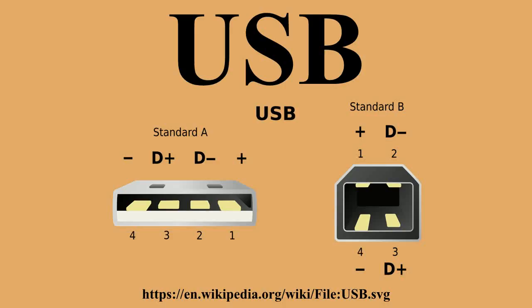An alternative to this is a compound device, in which the host assigns each logical device a distinctive address and all logical devices connect to a built-in hub that connects to the physical USB cable. USB device communication is based on pipes. A pipe is a connection from the host controller to a logical entity found on a device and named an endpoint. Because pipes correspond one-to-one to endpoints, the terms are sometimes used interchangeably.